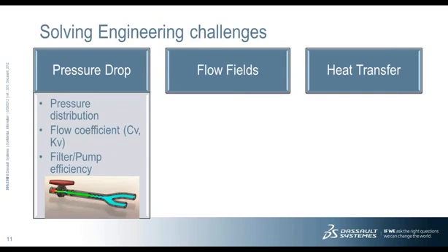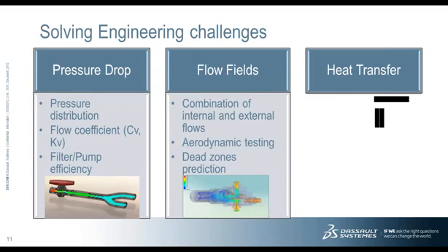For example, the objective of a duct design is to size the ducts so as to minimize the pressure drop through the duct while keeping the size, and then the cost, of the ductwork to a minimum. SolidWorks Flow Simulation helps designers investigate and optimize pressure distribution in a wide variety of products such as valves, nozzles, control devices.